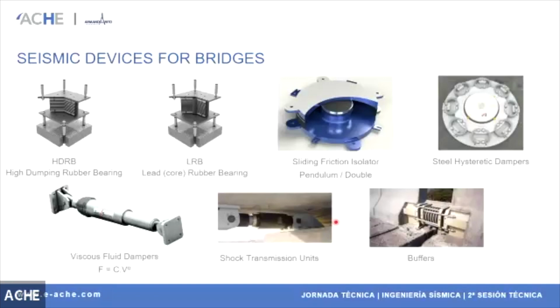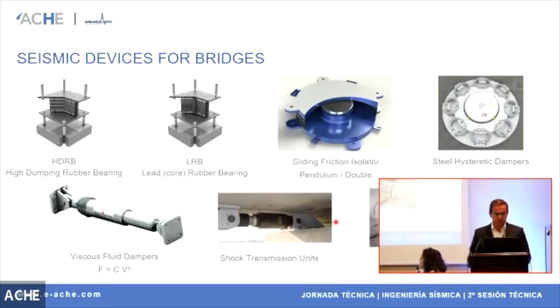Well, seismic devices for bridges, we have a lot nowadays. You have outside most of the suppliers of seismic devices. I will not talk a lot about this, but what I can say is that you can use whatever you want to achieve your results. Mostly you can block some piers, you can free them for seismic, or just block them for the quick actions. And well, you have a lot, but you should, as I told before, keep it simple and maintenance free.